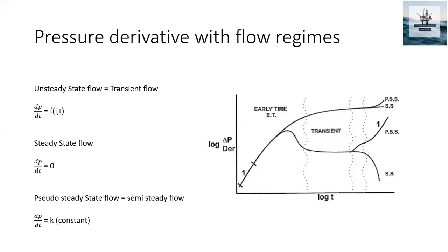So this pressure disturbance, which was generated near the perforations, will slowly migrate towards the end of the drainage area. While transferring this pressure disturbance from wellbore to drainage area, the transient period that we are seeing is the condition that we name unsteady state flow.